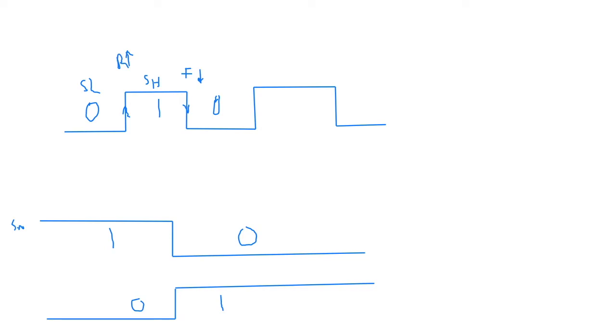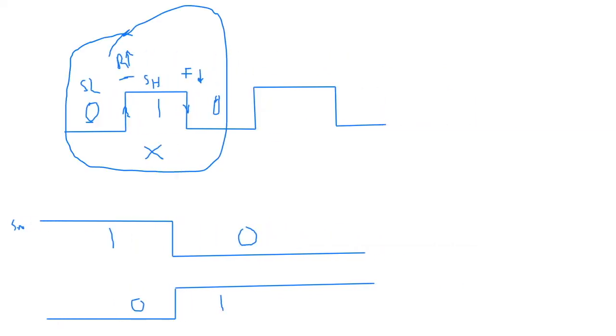So we've got the stable state low, we've got the stable state high if we want, but we may not actually use this. And we've got the rising edge, we've got a falling edge, or we can say any change at all, it should respond. So as soon as I make a change, it responds. And we are referring to the external interrupt, or whatever signal is generating the external interrupt. In this case, we can use a switch as an example. I hope you understand that.